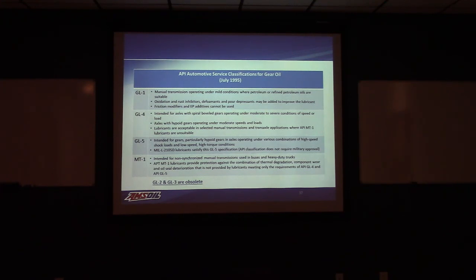We jump right up to GL4. GL2 and GL3 have been discontinued. GL5 is probably the most severe out there, and that's for hypoid type applications, a lot of sliding pressures and so on and so forth. Basically, it's when you run into a high demand for what they refer to as extreme pressure fluids. Won't define those right now.